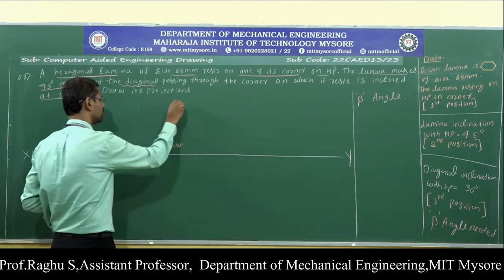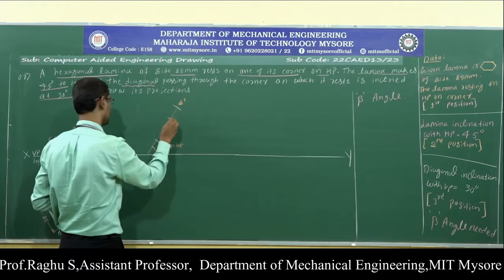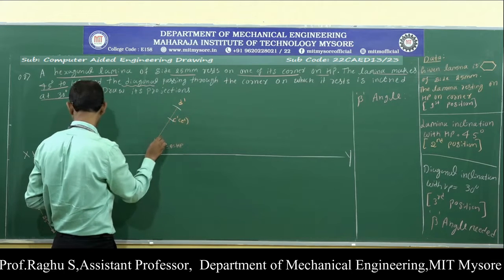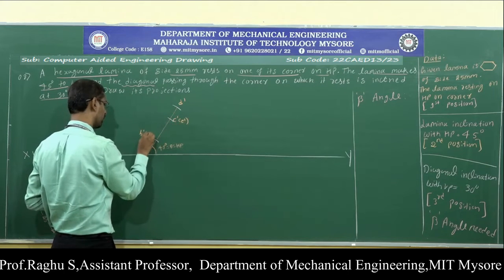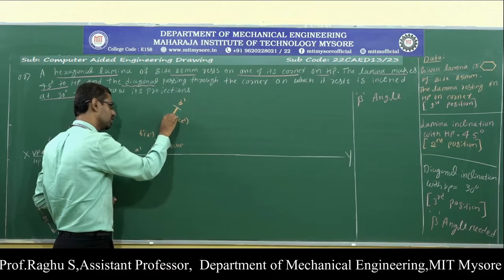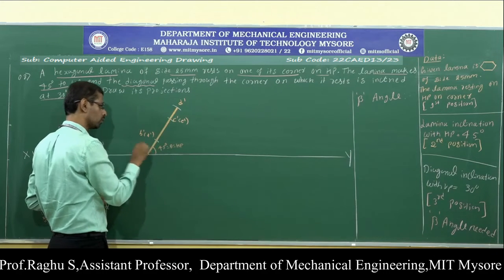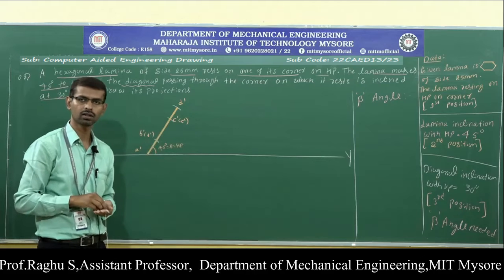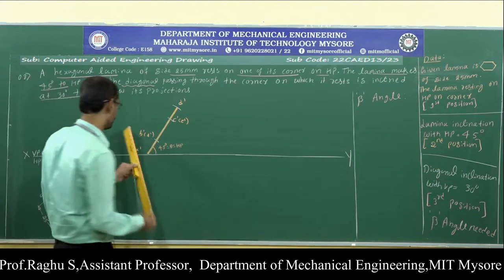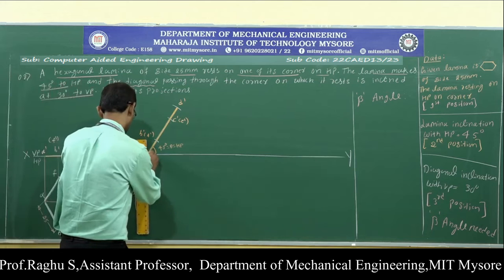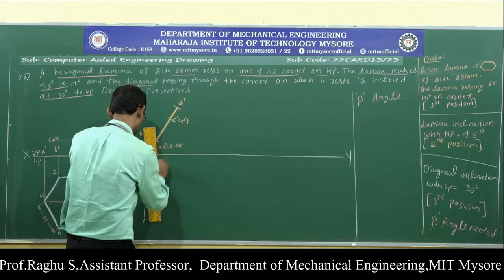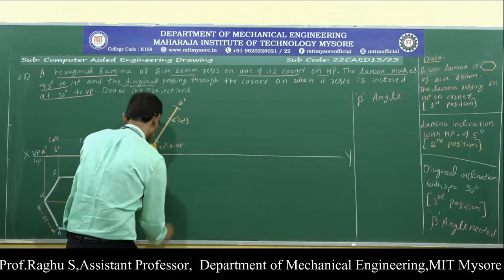Therefore, this is the point D dash, this is the point C dash and E dash, this is the point B dash and F dash, and this one is point A dash. Make it dark since it is the view, the second position front view. Next, draw vertical downward projections using thin lines. Projection lines mean thin lines.